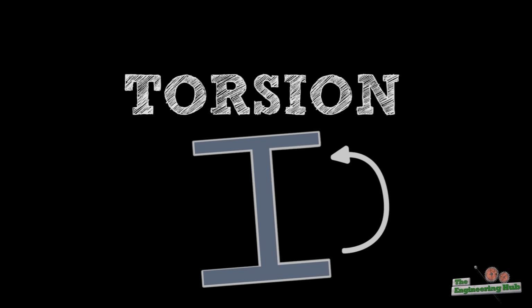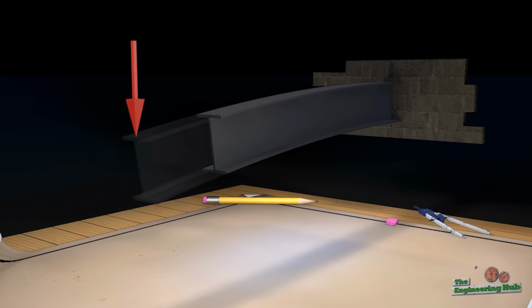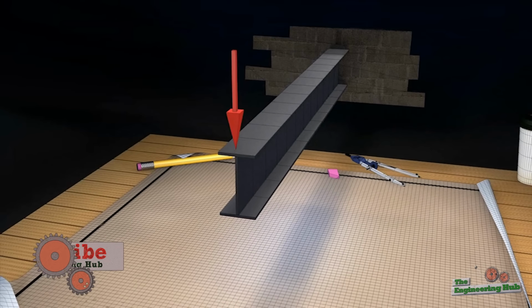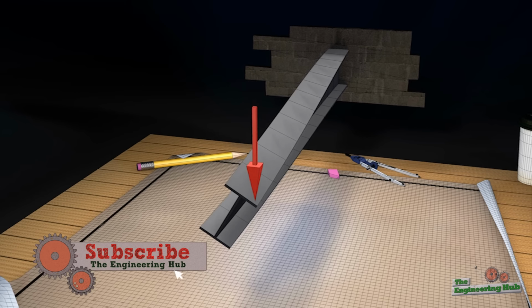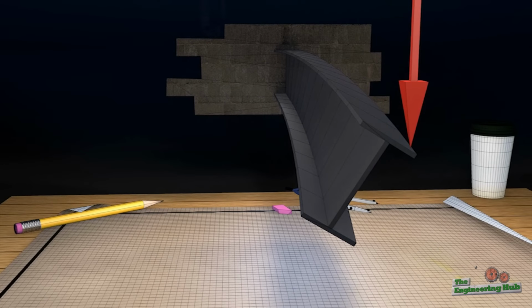However, the I-beam still has one other flawed property which causes even more problems than buckling. Until now, we've been applying downwards loads to the I-beam straight on top, in the middle of the web. However, in practice, beams can have load applied slightly off to the side. Engineers call this eccentric loading. This eccentric load causes twisting or torsion on the I-beam.